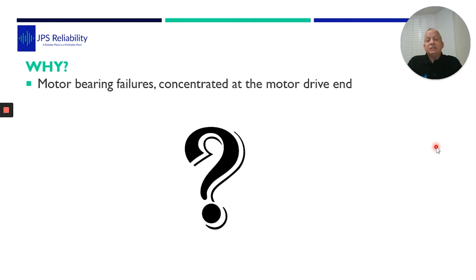Then the energy efficiency team did some tests, and they worked out it's more energy efficient to run it slower. So all they've done now is, instead of running up through a resonance and being on the top end of a resonance, where the pump and the bearings can just take it, they've slowed it down and pushed it into a resonance. So now they're running 24/7 at its resonance.